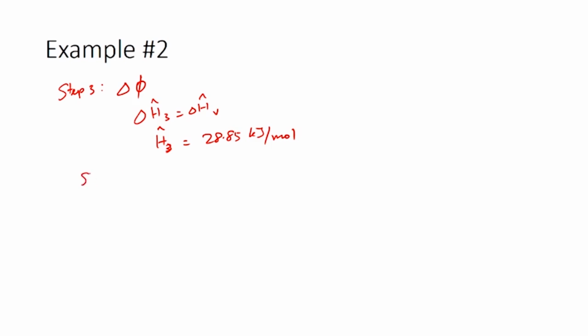Now the step 4, which is delta T, where only temperature changes and phase and pressure are constant. H4 cap is integral Cp dT. However, here it would be the Cp of hexane vapor, and temperature increases from 69 to 300 degree Celsius. You can get the Cp value from the tables or from some handbook.